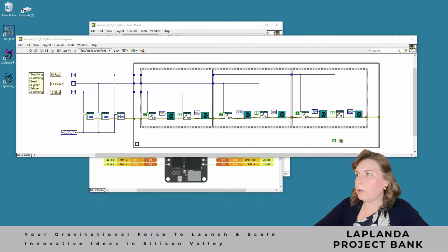And yes, before connecting real LEDs, I'm currently using the LEDs on the board itself. I have a reference here. I set the red LED to digital output 23, the green to 24, and the blue to 25. And now let's save it.